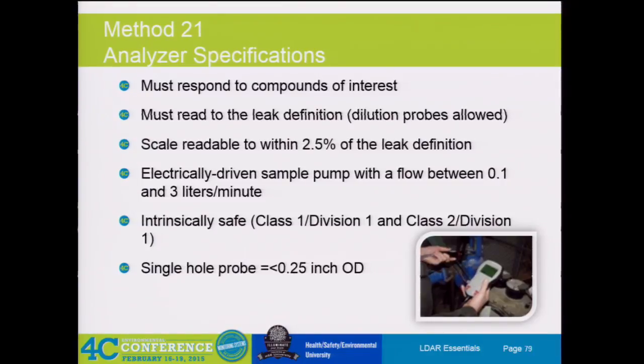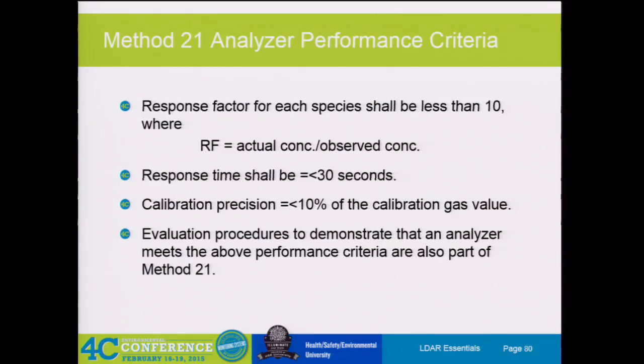So they were constricting the flow into the machine and reducing the amount that it was leaking. And so by removing it, and then we did a comparison out in the field, we were seeing almost perfect agreement. But when they had it on, we were seeing between about 20 to 30% difference in readings. So it's just something to consider also on this point.